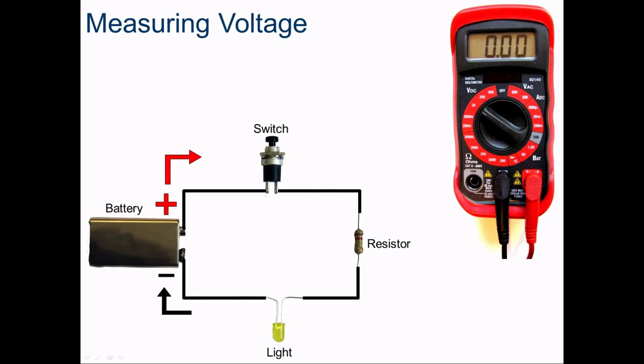Let's discuss measuring. Measuring voltage. We'll set the multimeter to the proper voltage range. Notice this is a DC current, a DC battery, right? Not AC, which would be what you would find in your house. So for DC, we set it to 20. We always set it to the setting just above what we think we're going to be measuring. For example, for a 9-volt battery, the lowest setting is 20. We don't want it at 200 or 600. We'll set it at 20.